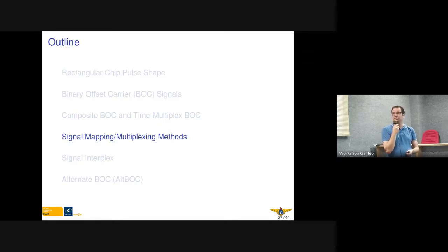However, as I mentioned also yesterday, there are methods that can be used in the receiver to combat this interference. We can use multi-user detection and mitigation in the receiver. As we're estimating all the parameters of all the received signals, we can use this to subtract this interference from the incoming signal, and thus also mitigate the multiple access interference. But this is work in progress.